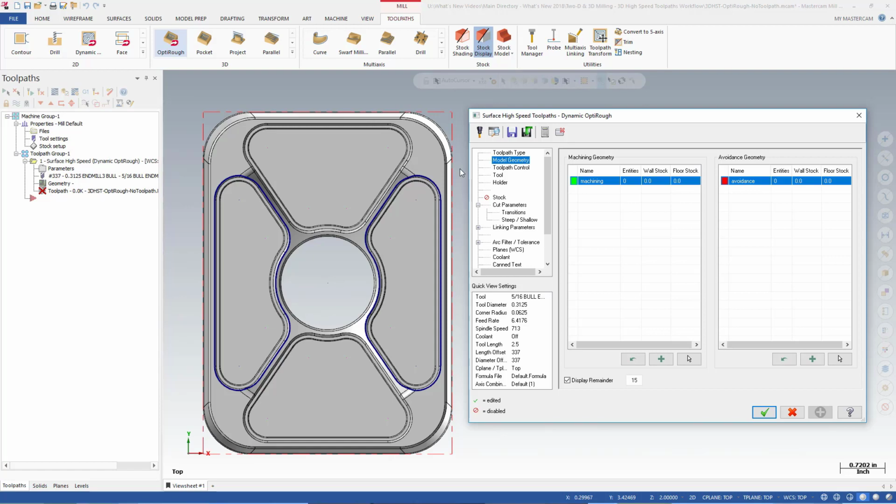When you get to this page, you start selecting geometry. In the graphics window, you will notice that the model geometry has changed to white. Display remainder is active and using the default color. So any white geometry you see has not been selected for this toolpath. The group and remainder colors display only when you are working in the Model Geometry page. If you move away from the page, the original colors assigned to the model return.